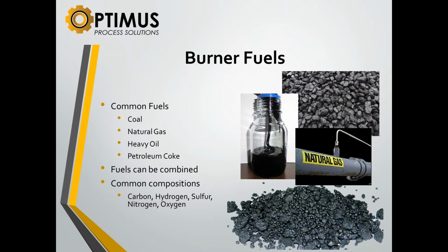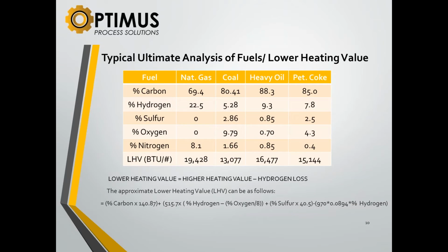I've had some questions on the sizes of the solids. Is there a particular size of the solids? Generally, whether it be petroleum coke or coal, you want to grind that down to about 200 mesh or better, because you have to blow it in with the primary air in the burner tube. And if the particles are too large, it takes too long for them to burn. Right. So the finer they are, the quicker they burn, the more luminous flame you get. So you want the fuel to be dry and a particle size below 200 mesh. I see.